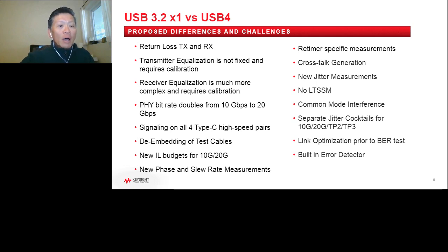There are new insertion loss budgets for USB 4 at 10 and 20 gig, and I'll share that in the following slides. There are many new measurements. There are new phase measurements, slew rate measurements, retimer specific measurements, jitter measurements. Again, I'll talk about these in the next slides.